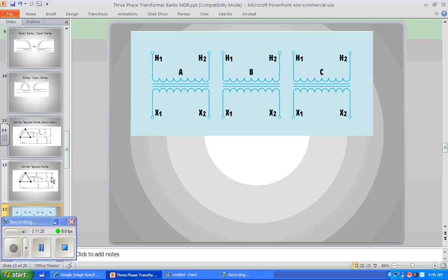And then we're going to find the current, because we'll know the impedance of the load. In the past, we've only talked about pure resistive loads, and for simplicity, that's easier to look at, right? But what we want to do is look at what would happen if we had a motor on this. We would have an inductance and a resistance. We'd have a triangle problem, right? And so we're going to start looking at how we calculate the triangle at that point and find out what happens there and start taking that information back up.